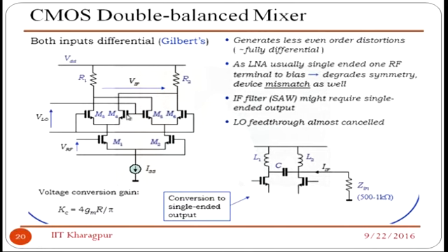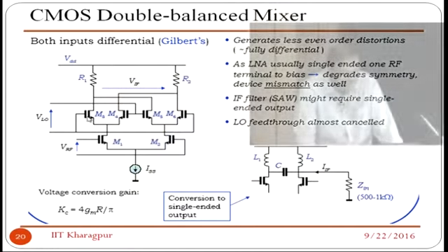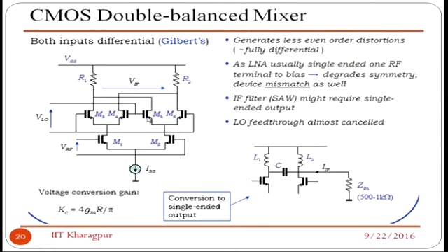So the gate terminal of M4 is cross connected. So M3 and M5 form a differential pair, M6 and M4 as well, and then finally the currents coming out of the differential pairs cancel each other, and they provide you harmonic cancellation very wisely. That is the Gilbert configuration.